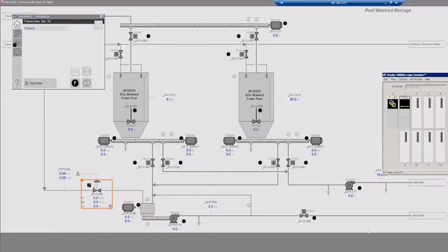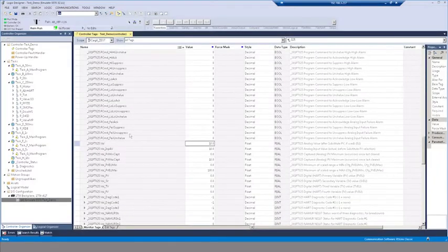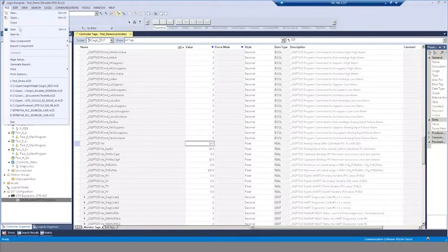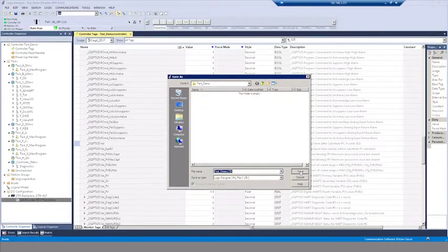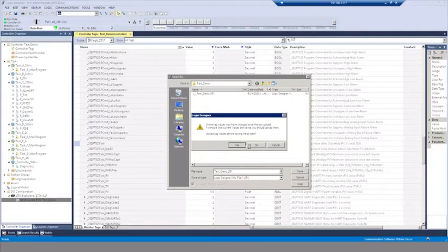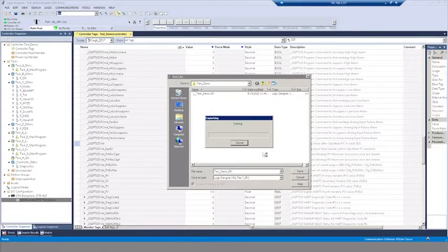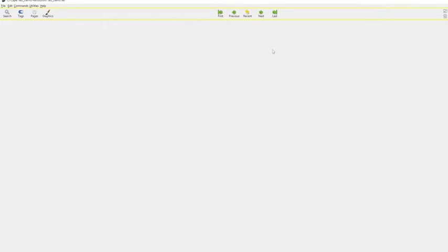For this example, the process we will be looking at today is a simple Rockwell system with an HMI screen and one emulated controller. In order to be able to establish communication between VP-Link and the Rockwell controller, we need to extract the I/O tags from the controller and download them to the VP-Link program. This process of extraction shown in this demo is similar for other control systems. VP-Link has various extraction tools for different control systems, making it easy for users to test their various system components.